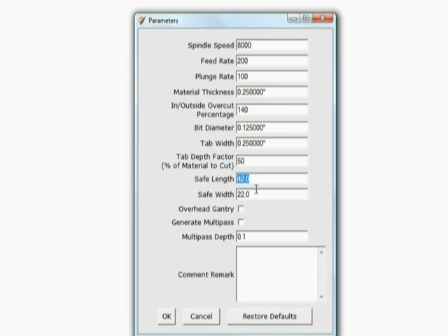In actuality, by the time I trim my fan fold out of my bundle, it's going to be more like 23, maybe 22.5 inches. What I'm doing is setting up these two measurements here, which set up my bounding box. They tell me basically that the parts have to fit within this. If I have any parts outside of this boundary, then the machine's not going to process the code in those areas. So I know for a fact that my width is going to be about 22 inches from the sheet when I load that sheet into my flat printer, nice and straight and true.